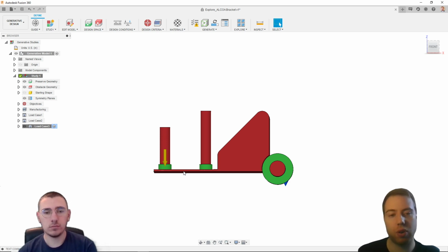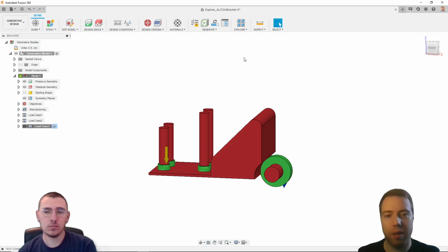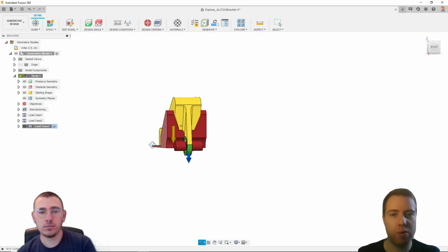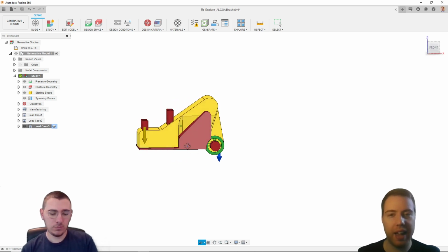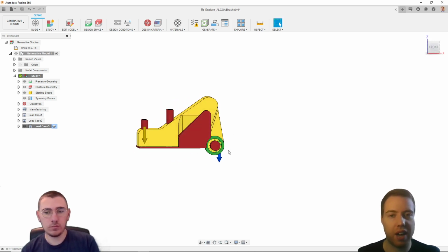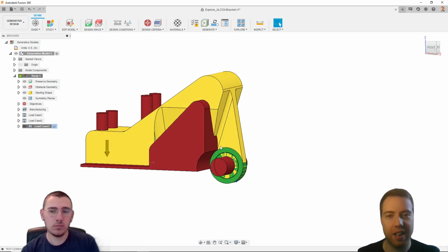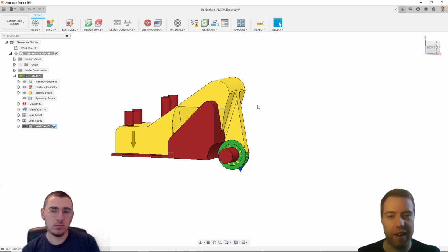So we need to make sure that our preserved regions don't become separated. In a case like this, where generative design might struggle to find its way around this obstacle region, it can be really useful to create a starting shape. All this starting shape is doing is helping it get around that shape, if that makes sense. And it's giving it a starting idea that makes sure that it goes in the general right direction.